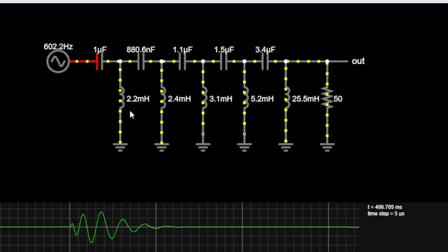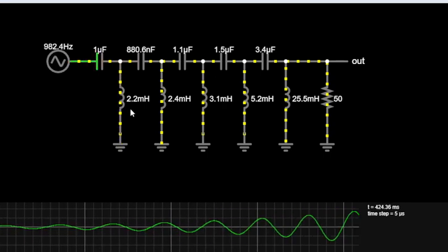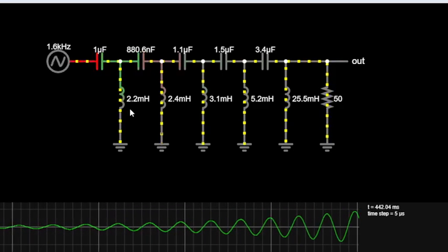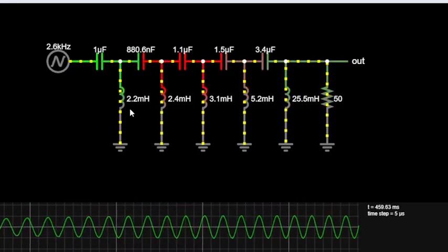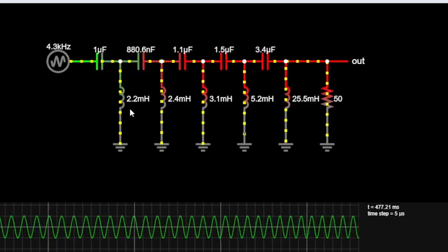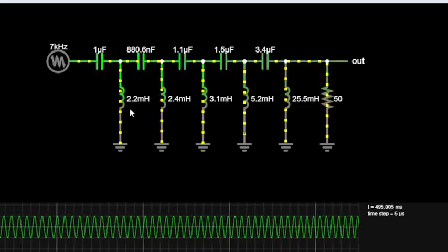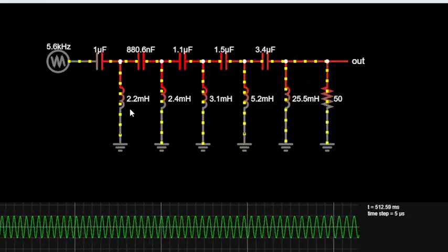first and then inductors. Before starting, we first need to know that a Butterworth filter is a type of filter commonly used in signal processing. It belongs to the family of filters that have a maximally flat frequency response in the passband. The pole in the filter refers to its order or complexity. In our case, we are focusing on the 10 pole Butterworth high pass filter.